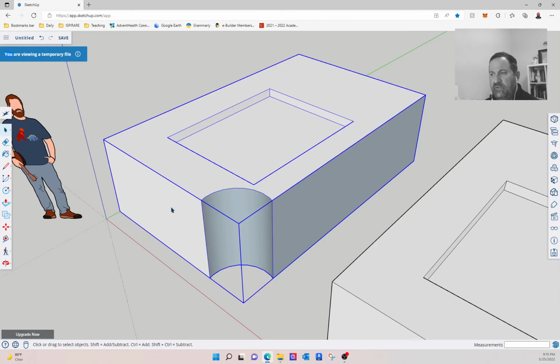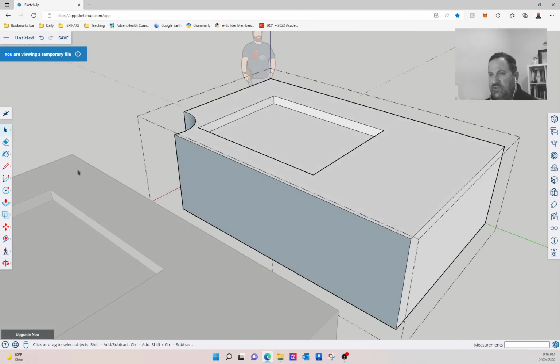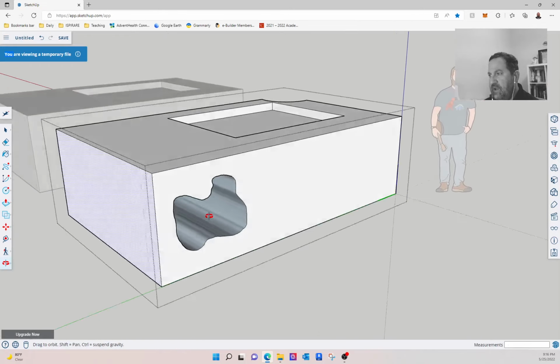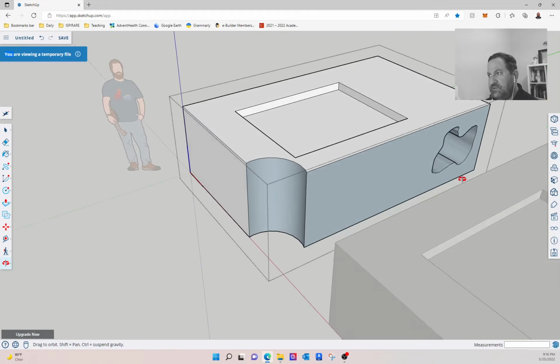And then also, Boolean operations could be in the form of a through body change. So using this line tool, which is different, I can make whatever shape or polygon I want. I can also make a scribble like this guy, right? As long as it's closed. That creates a surface. I can then push that surface all the way through to the other side, and now I have a hole. So that is also a Boolean operation.